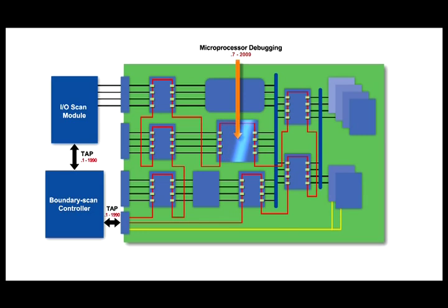For devices like microprocessors, it may be desirable to control the power consumption of the debug logic or to quickly access a specific IP block on a system-on-chip device to improve the software debugging performance. This additional functionality is defined in IEEE Standard 1149.7 and can be accessed through the JTAG port, or, alternatively, through a reduced pin count TAP defined in .7.